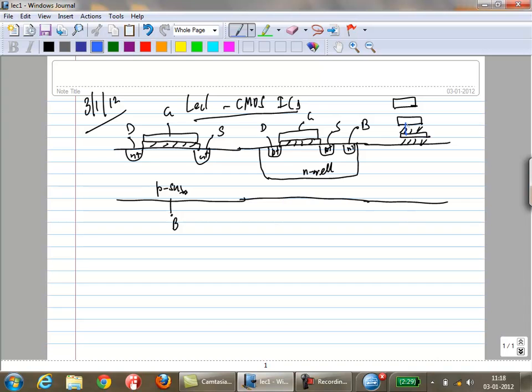Then you do what is called a via. A via basically takes you from one layer to the next layer. Similarly, you would have a different kind of via if you want to connect these. So these will be called M1. Modern IC processors have something like 5 or 6 layers typically, because you have a lot of complex circuits and want to make a lot of connections, so they typically have a lot of layers.